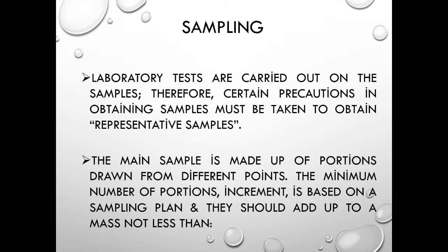The main sample typically is made up of portions taken out of different points in the stockpile. And then again, these individual incremental samples are mixed to ensure that we have one composite sample representative of the total material in the pit.